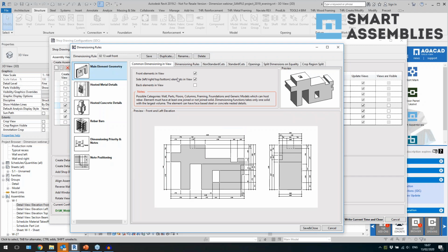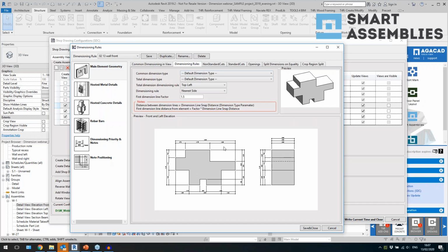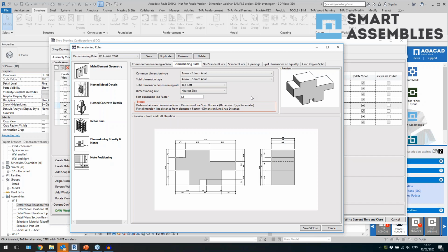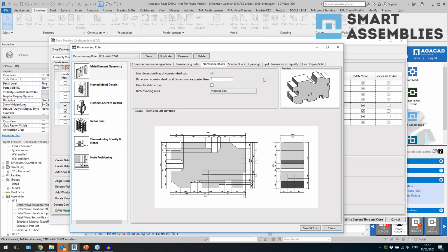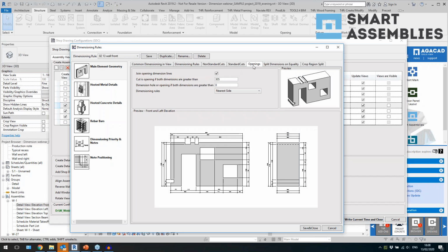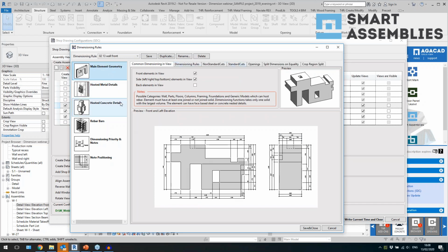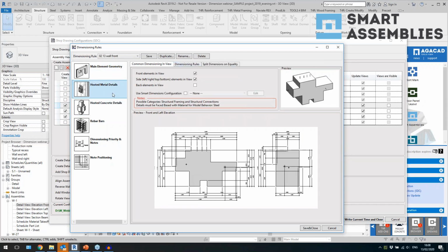And here what I have, in the main element geometry, I have settings how to dimension cuts and openings in my wall, what dimension style should be used. So I'm gonna use metric units here, but you can use imperial, doesn't matter. I mean, that's Revit stuff, right? Then some settings for the cuts and openings. I can define what should be the smallest size and so on. But it was okay with opening, right? I have door, so it was dimensioned pretty good.